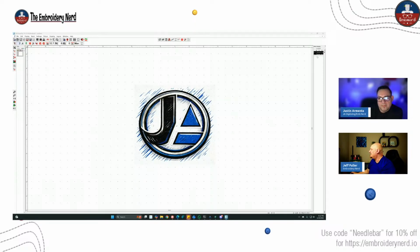And you can see up here on the upper right, this is basically your stitch display. So when you start this up, it's like a stitch list of all the stitches that are going to be in that object. So I've placed that first, and now I want to digitize an object, and so I've entered the complex fill. With this, I can come up here and you can have presets, and you can put in as many of those as you want. If you had something for puff, you could save it as puff, and that would be all your settings for that. So I just selected that ahead of time, and now I'll come around and start drawing the object here.